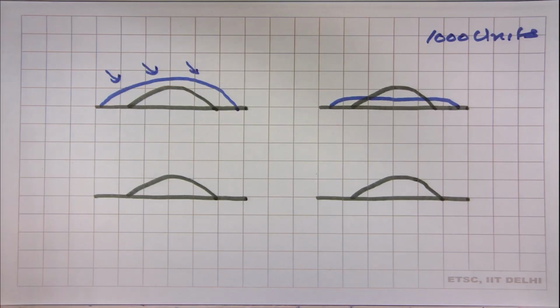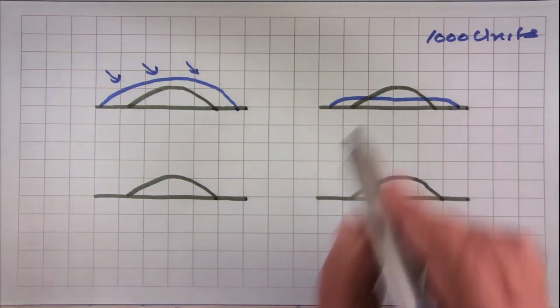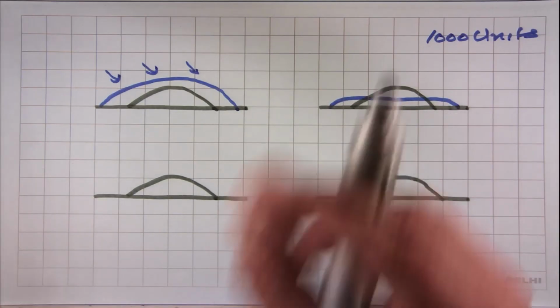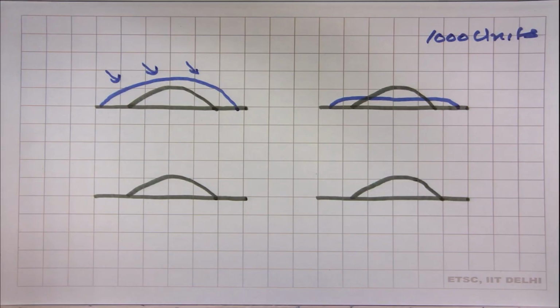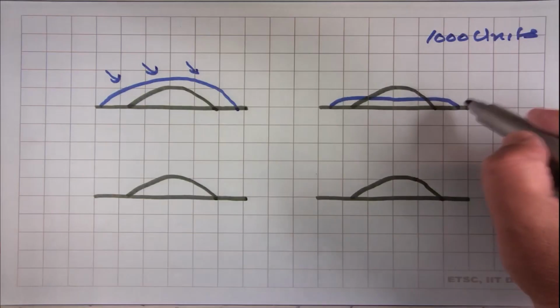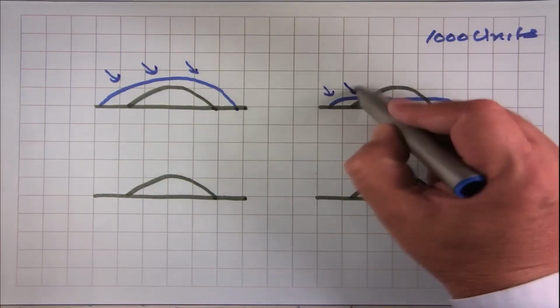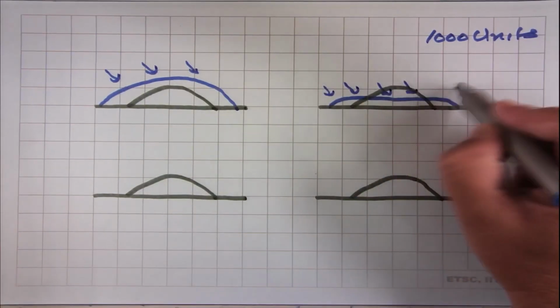Yeah, the one which is spread more, because the rainfall will be, let us say, 100 mm. It will have to be multiplied by the surface area over which the water is falling. Now, if the same waste dump is coming down in height but is being spread more, then the area over which it is spread is more, and quite clearly the leachate which will be formed by this dump will have greater impact.